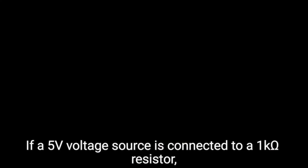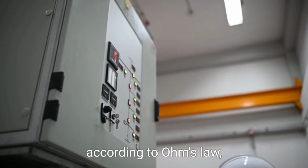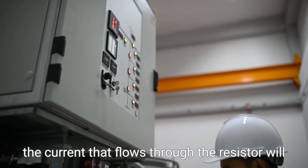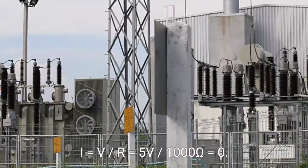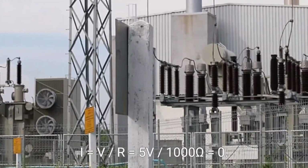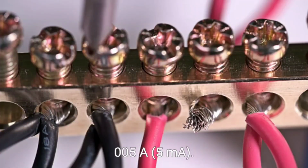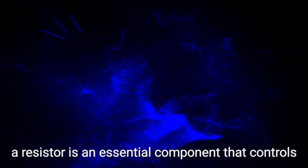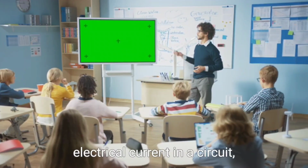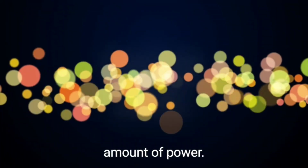Example: if a 5V voltage source is connected to a 1 kΩ resistor, according to Ohm's law, the current that flows through the resistor will be I = V/R = 5V / 1000 Ω = 0.005 A, or 5 mA. In summary, a resistor is an essential component that controls electrical current in a circuit, ensuring that other components receive the correct amount of power.